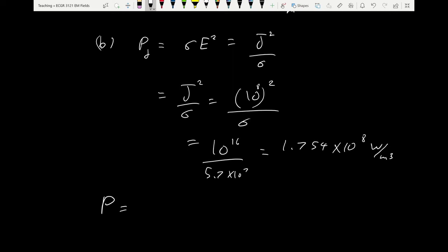that is lost in the neck of the fuse, just as the fuse is disconnecting? Well, it's the power density times the volume. The volume at the neck is going to be T times C times D, right? So remember, we had the neck here, so this is T, this is C, and D is how long the neck is.